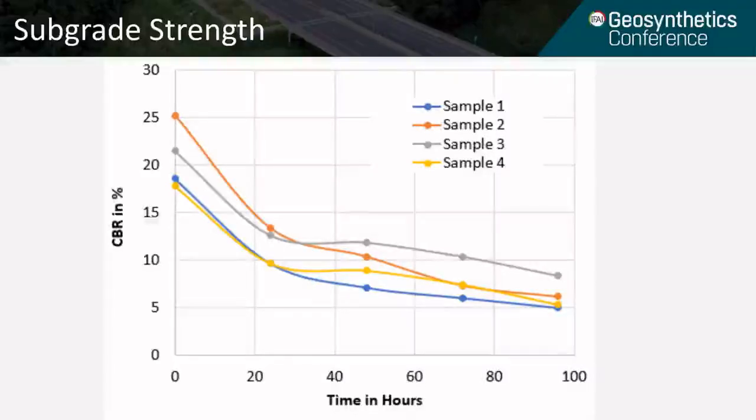Sometimes, depending on where a project is located geographically and when they plan in the year to stabilize soft soils, I often provide the project team with both a dry weather and wet weather section. There are some products or adjustments to section thicknesses that may be required for successful installation in less than ideal circumstances.